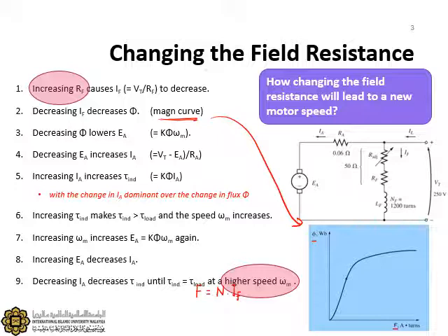So actually we can replace this MMF. If I remove this MMF, you can put IF here, and the unit is ampere. This will retain the shape, although the scale might be changing. The shape of this curve will stay the same. So now we have magnetic flux density here on the y-axis against IF on the x-axis.